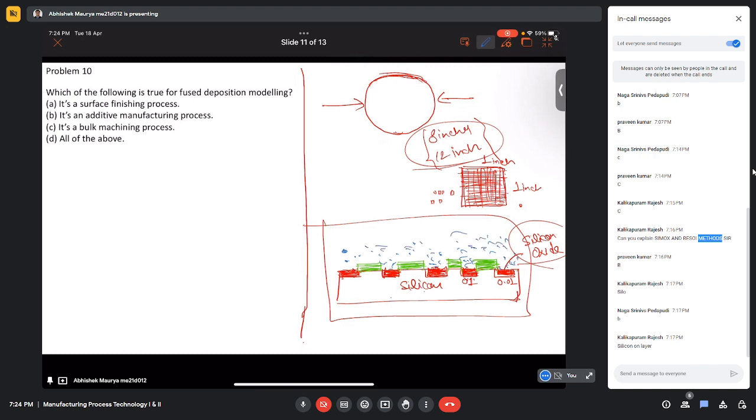Then this oxygen is going to react with the nascent silicon wafer surface, and it will keep diffusing inside the silicon wafer. How much depth it will go depends on the concentration of the oxygen we are creating here, as well as how long we are exposing this surface to the oxygen atmosphere, the temperature, and the surface finish.